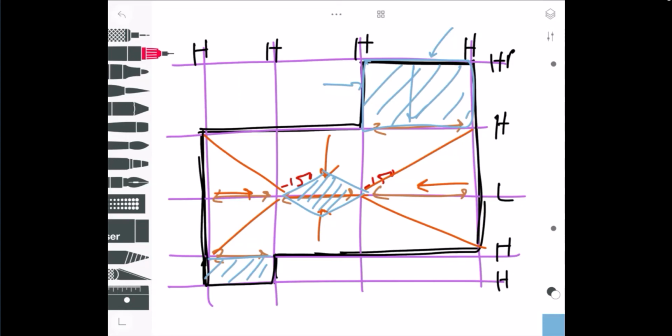There are cases where it's not feasible to slope the structure at all. It's just way too complex and it's not working out. That would be an example of where you go to a sloped insulation package. But certainly this is the approach, and you just have to play with it and think about it and see if something can be done.